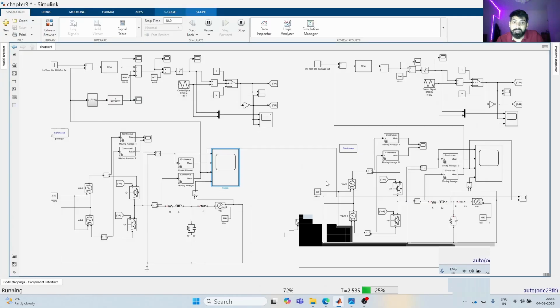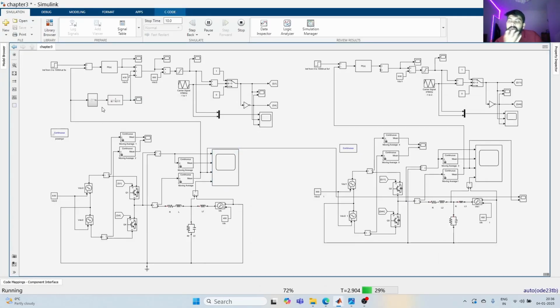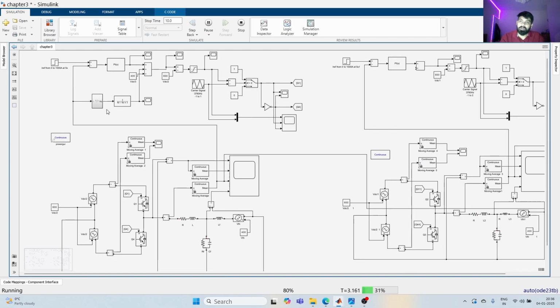So what we have done is that this system will give me the characteristics of the AC system, the information of it, and feed it to our compensator. Give the change in the terminal voltage, to mitigate those oscillations due to the poor damping characteristics of the AC system.